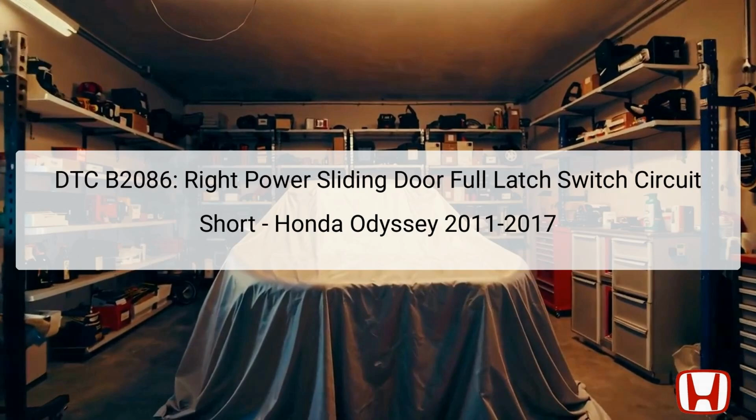The DTC B2086 indicates a malfunction in the right power sliding door full latch switch circuit. This issue typically manifests in the Honda Odyssey models produced between 2011 and 2017. The right power sliding door full latch switch plays a crucial role in the door mechanism, allowing for the secure closing and opening of the sliding door.